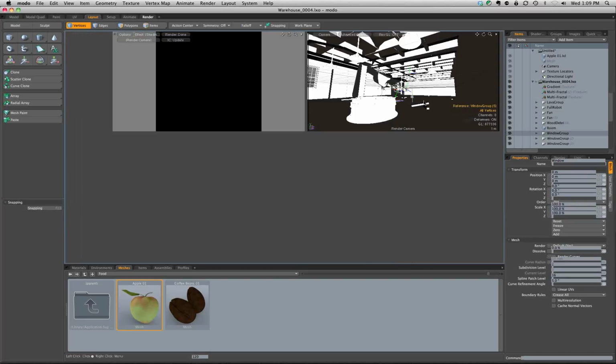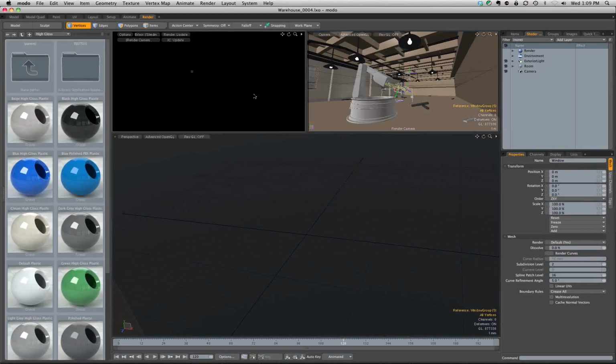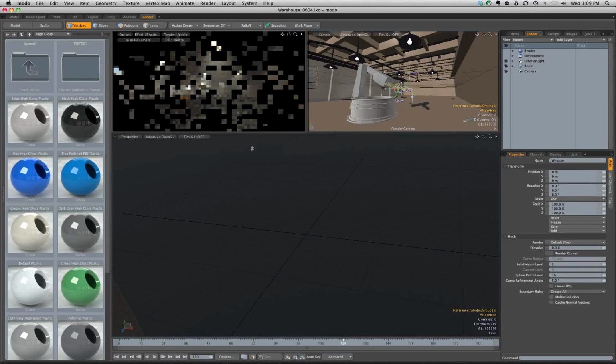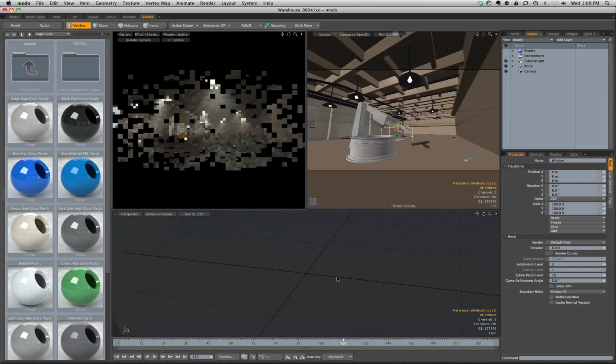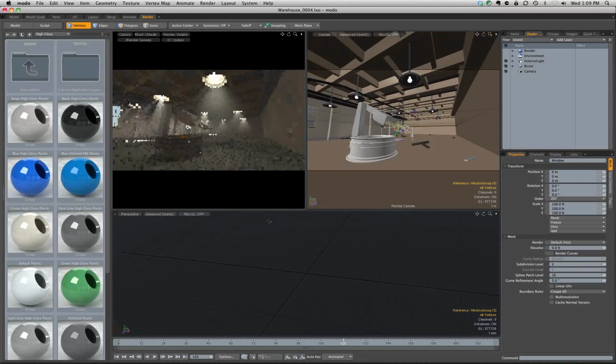You had in the render tab before just this quick little render, this preview. Basically what that OpenGL, that Ray GL, will do is give you that directly in your layout. Depending on your scene, you can change that. Sometimes turning off overlays and wireframes will help speed that up as well. But that's just to give you a good idea what this preview does.